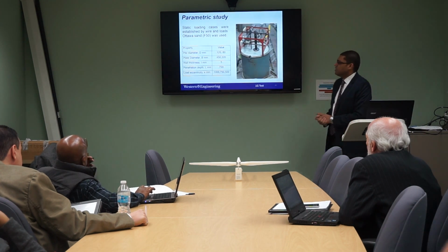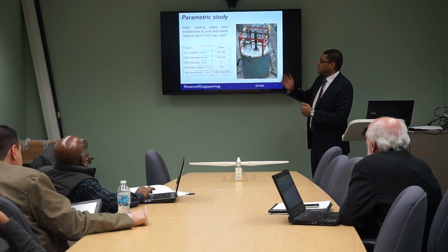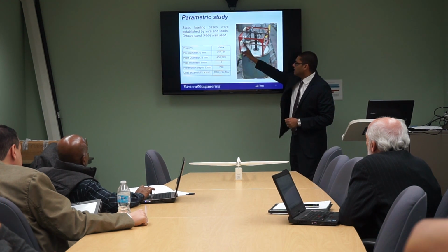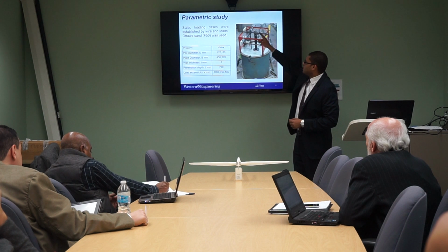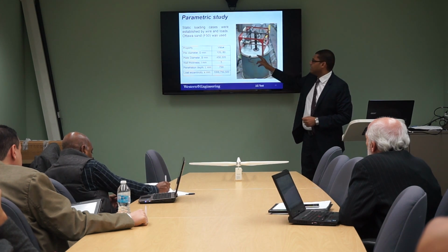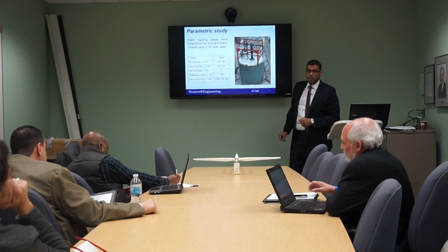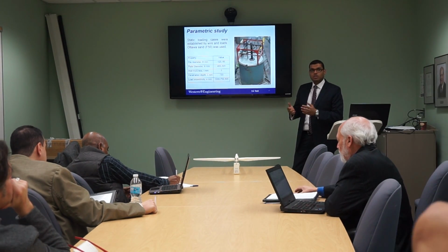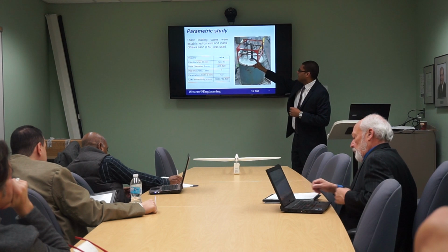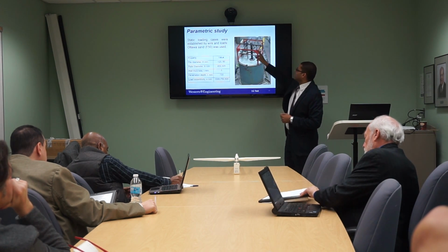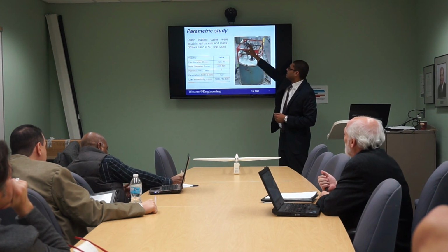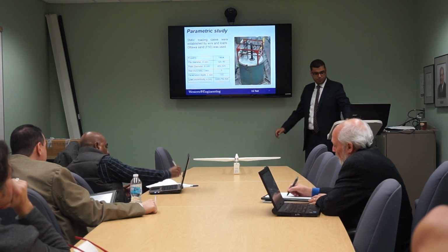We have done our test here in the structural lab using Ottawa Sand F50. This is our steel tank here, and this is our model, one of the models. In this case, it is a hybrid system. We can see the plate here is steel, not concrete, because we want the system to be just rigid. We can see this is the LVDT, and this is the actuator here to apply the load.